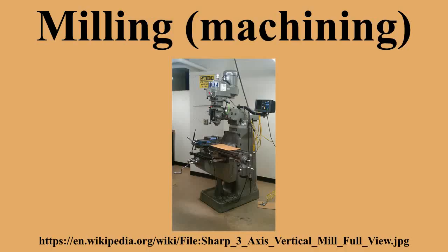Horizontal milling machines also have a C axis, allowing the horizontally mounted workpiece to be rotated, essentially allowing asymmetric and eccentric turning. The 5th axis controls the tilt of the tool itself. When all of these axes are used in conjunction with each other, extremely complicated geometries, even organic geometries such as a human head, can be made with relative ease with these machines.